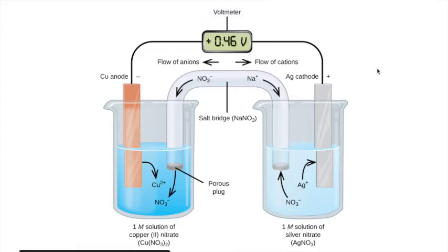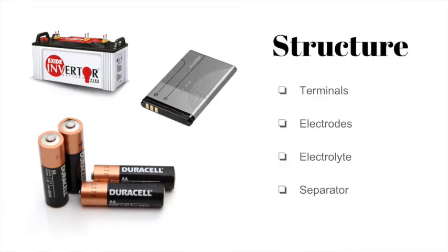An actual battery is just what we see in this chemical system being wrapped into a cylinder or a plate or a box. But no matter what shape it is, the basic components of the structure are always going to be the same. First of all, it definitely needs two terminals to connect to the external wires. But different from the laboratory beaker cell, these terminals are not pieces that directly react. They are connected to the inner electrodes, which are usually metal or some metal oxides that carry the redox reaction. And then we need the electrolyte so that the charged particles can be transferred. In modern batteries, the electrolyte has been designed into gel or solid form instead of solution to avoid leaking.